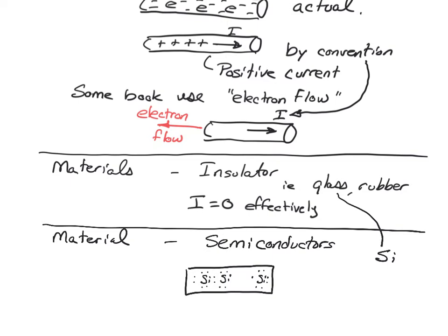They put an imposter in the silicon bond structure so that there's an atom in there that is not supposed to be there, but it turns out quantum mechanically it fits. So now we're going to do something that is, well, brilliant. Instead of putting another silicon atom in there, I dope this insulator. And I dope it with the next element up in the periodic table, and that's phosphorus.